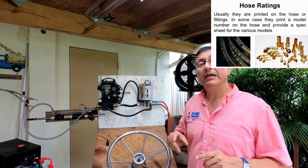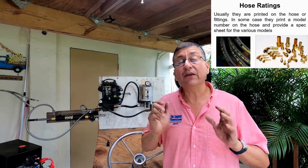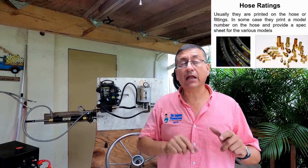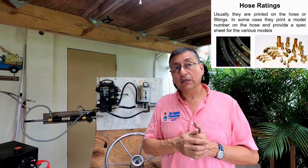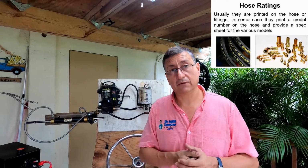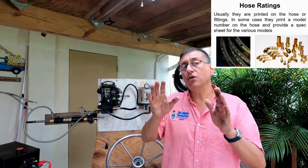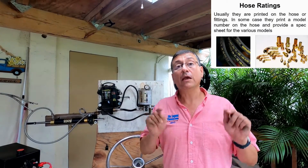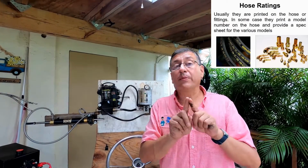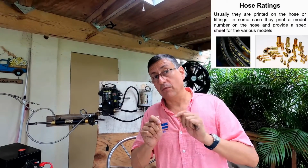If the fittings are in copper, should be bronze, naval bronze. Never use brass fittings. The fittings that you buy in the general hardware storage departments, those are in brass for residential application, for building construction. Those fittings are not recommended in marine applications because those fittings in contact with the aluminum and copper, no good, and the more noble metal attack the less noble metal.